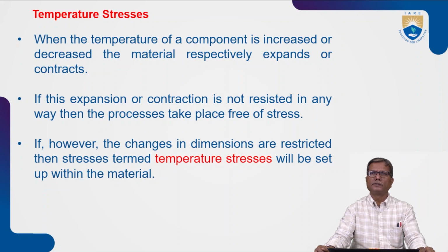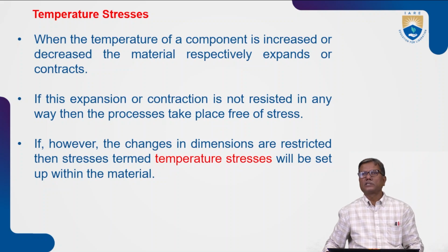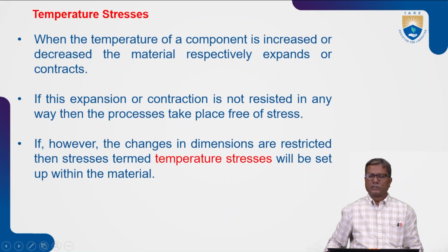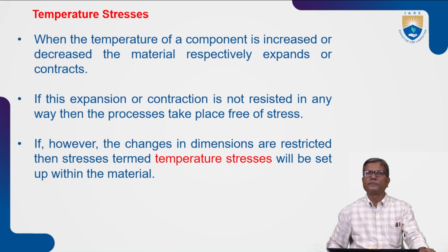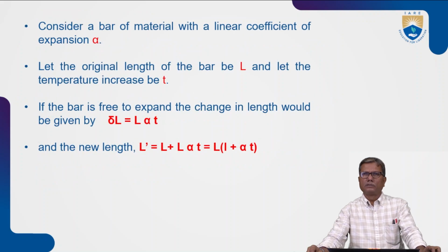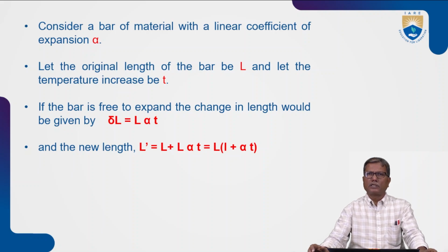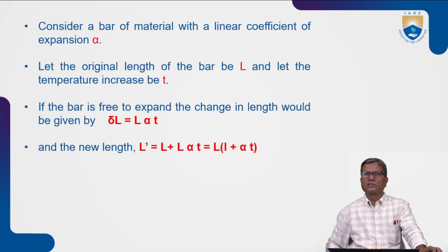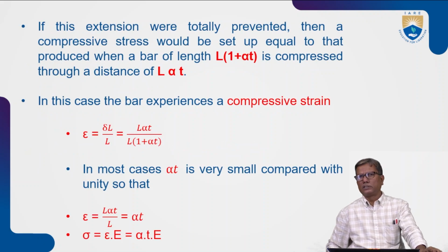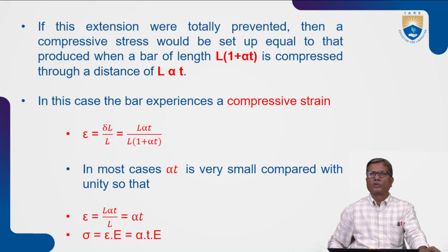Okay. So here, the temperature stresses which are induced in a metallic bar can be determined by equating the change in length due to temperature rise or temperature decrease to the force which causes that much expansion or contraction.